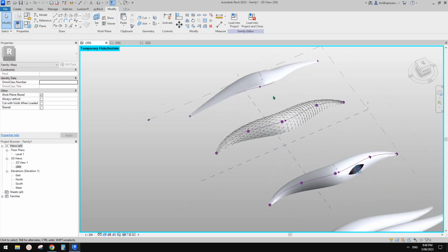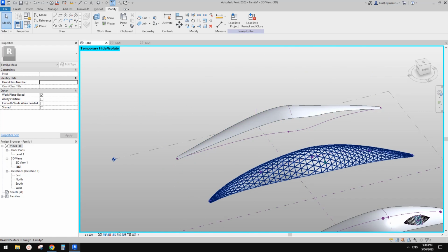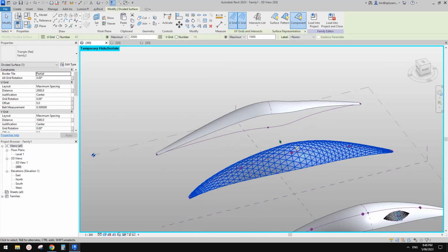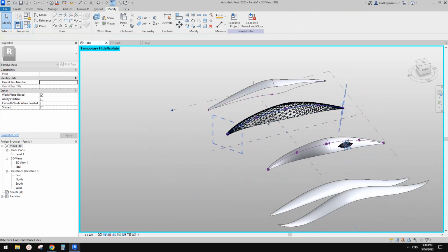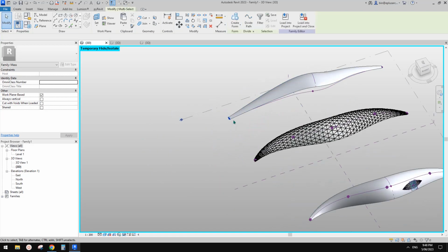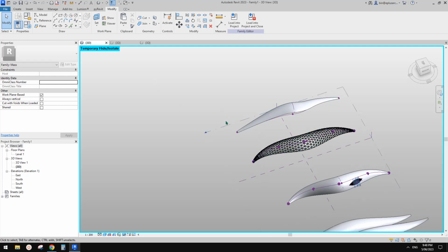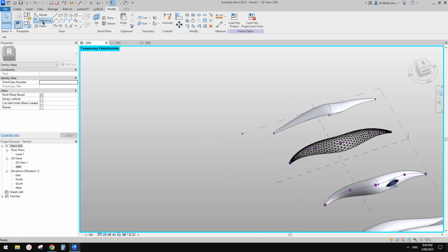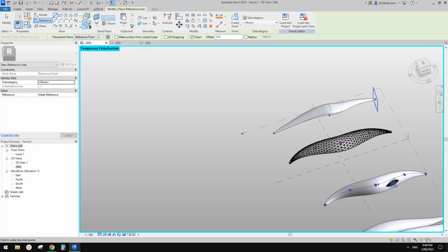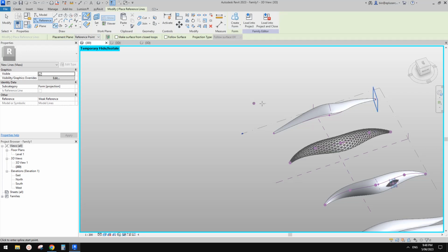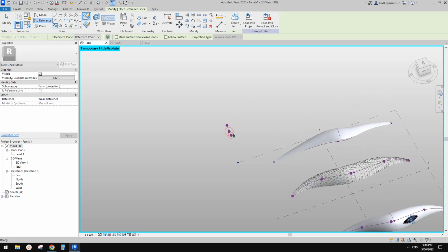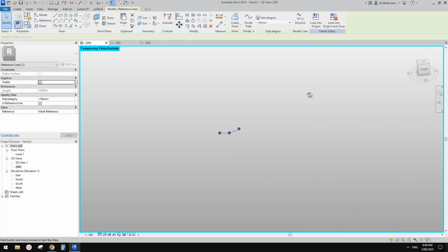And also, you can also build this shape without a path. So let me just copy this. Okay, Control C. Hang on. Maybe we can just do spline through points. So 1, 2, 3. Let's do that. So reference, I'll just use level as my work plane. Okay, so I'll place 3 spline through points, or maybe 5. I'll use 3 points. Hang on. Sorry, let's do it again.